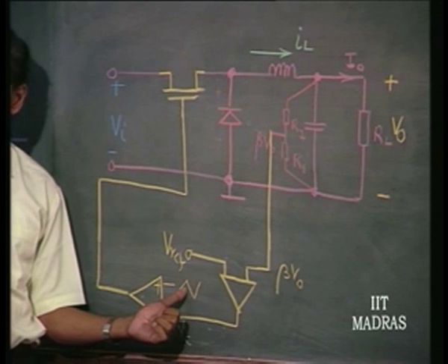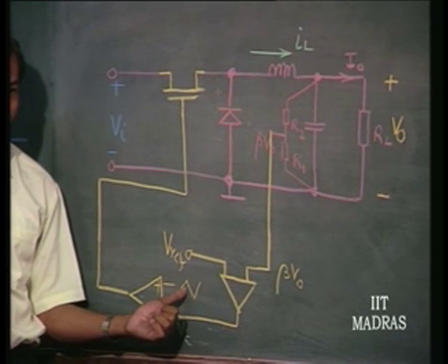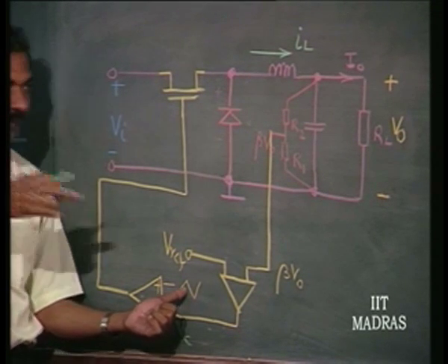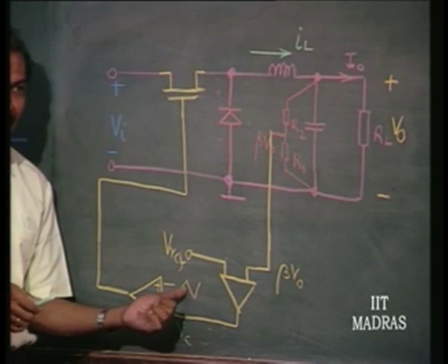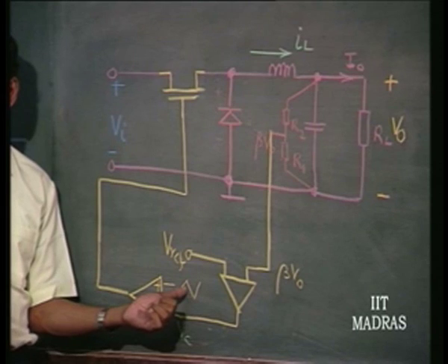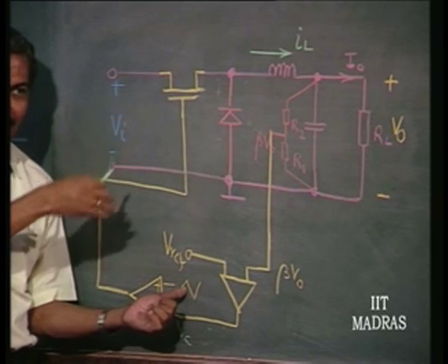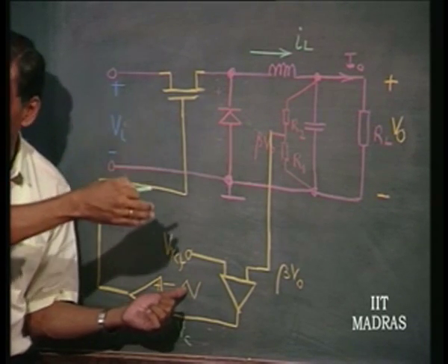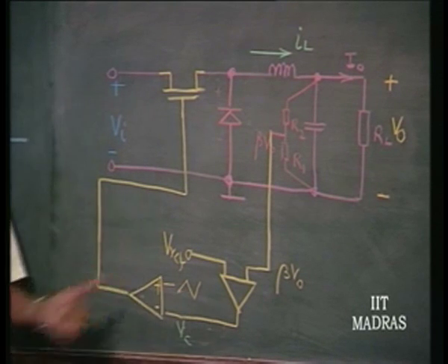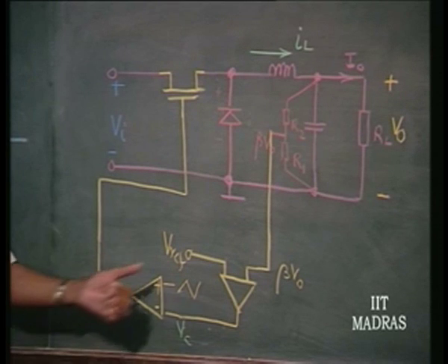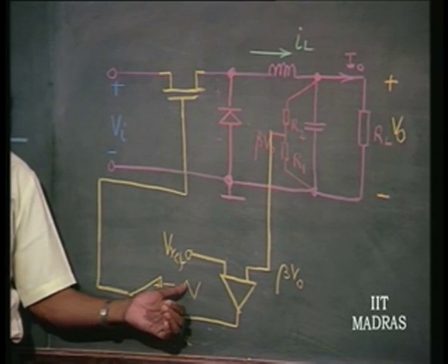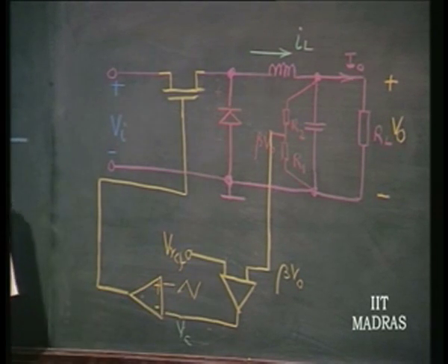So, here the frequency is known to you, the design frequency is known to you. If it is made a regenerative feedback structure and this itself is made an oscillator, then we do not know the frequency, and we have to adopt a complicated analysis procedure for finding out the frequency of oscillation. So, this is an externally controlled oscillation frequency, pulse width modulated voltage regulator, switched mode regulator.